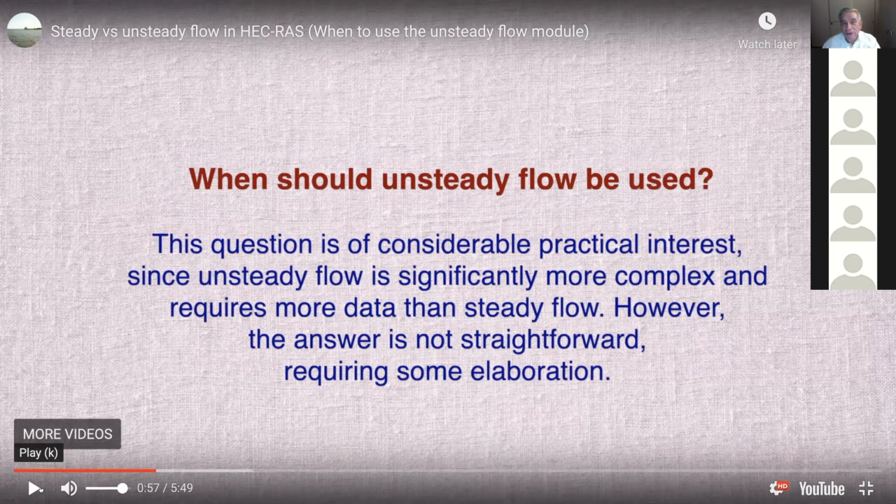Should you use steady or unsteady flow? Before you answer that question, you have to know your hydraulics. That's why you're here. Because if you don't know your hydraulics, you could say, well, take your pick, I will do whichever. And that's not the correct approach. The unsteady flow requires a lot more data. It is less robust. It could blow up on you, while the steady flow hardly ever blows up. Because of what Abbott was saying, you've got a lot of computations, all kinds of things could go wrong, right? The answer is not straightforward.